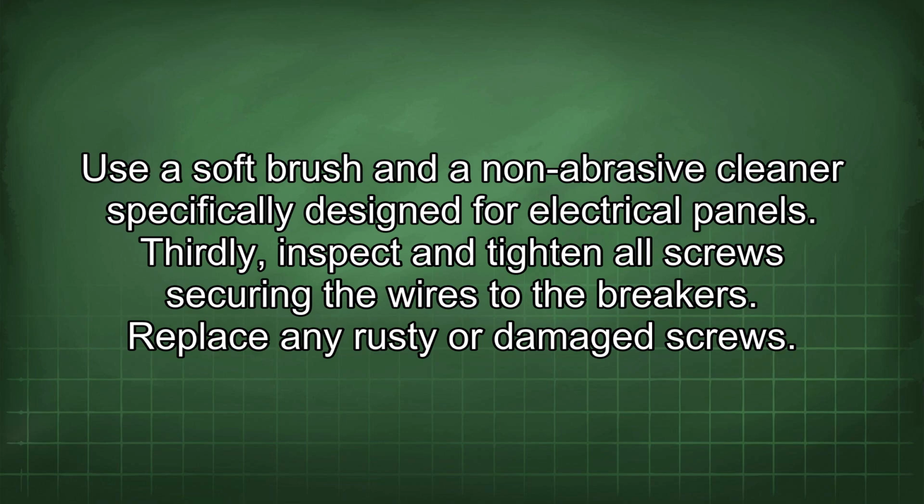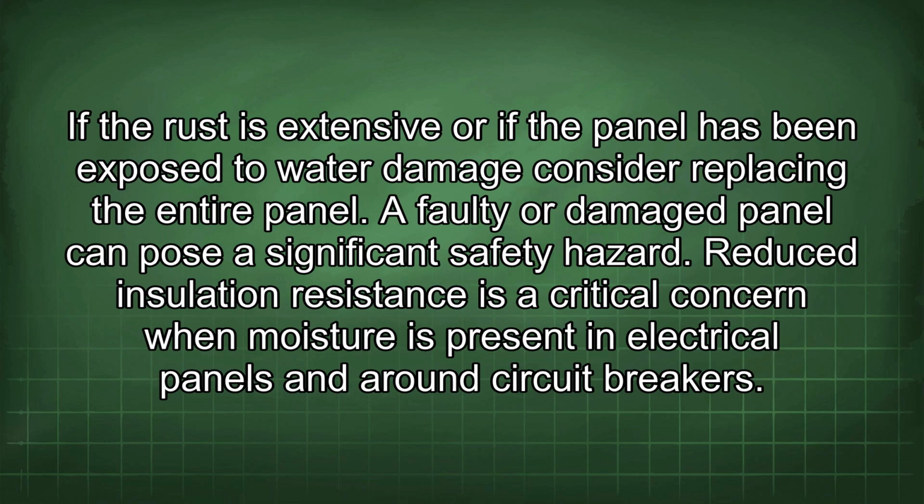Thirdly, inspect and tighten all screws securing the wires to the breakers. Replace any rusty or damaged screws. If the rust is extensive or if the panel has been exposed to water damage, consider replacing the entire panel. A faulty or damaged panel can pose a significant safety hazard.